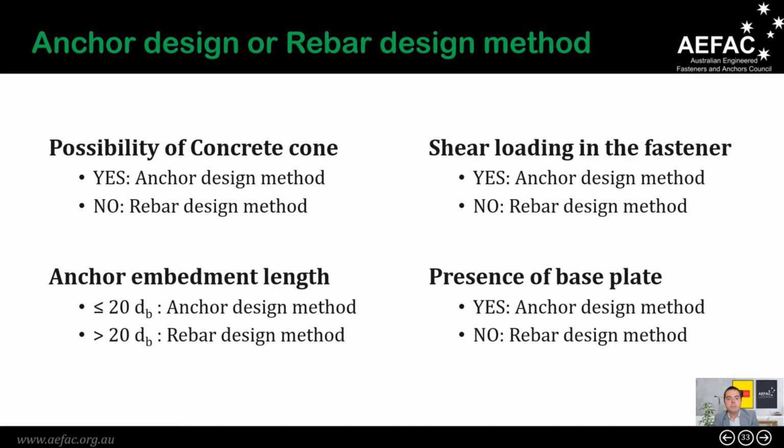And the requirement of shear load transfer from the fasteners: if yes, the anchor design method should be used. We have chapter 7 in the standard to design for the shear loading. If there is no requirement, we can use a rebar design method.